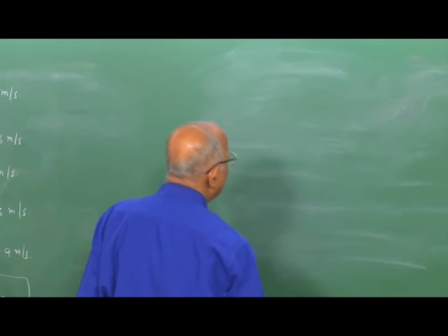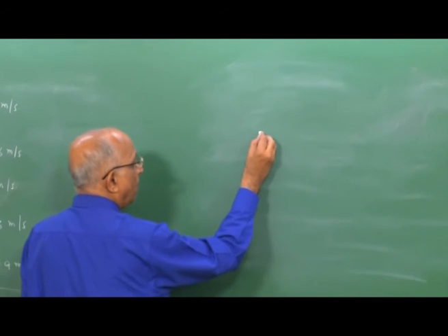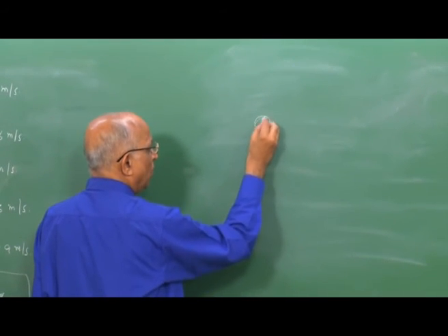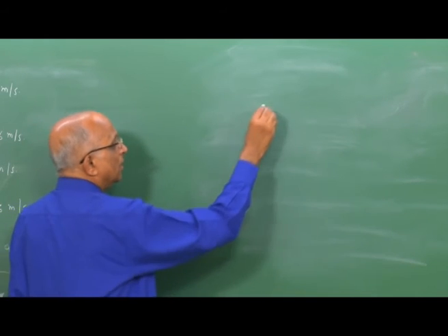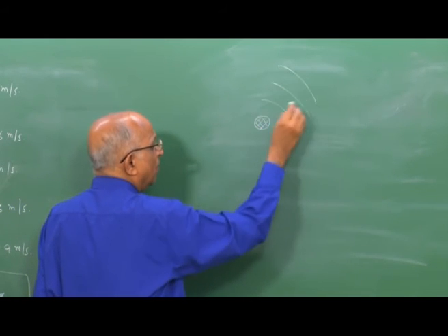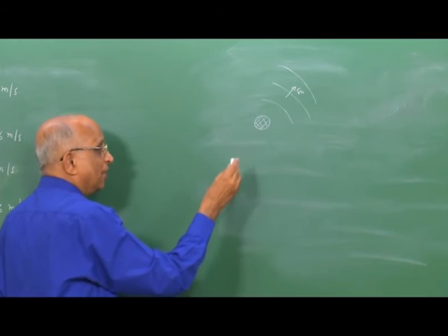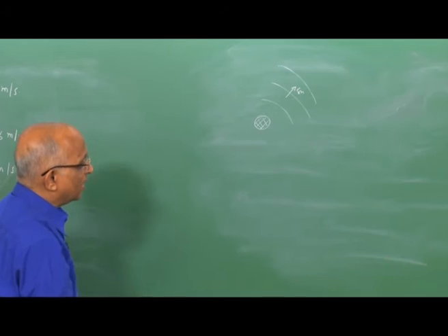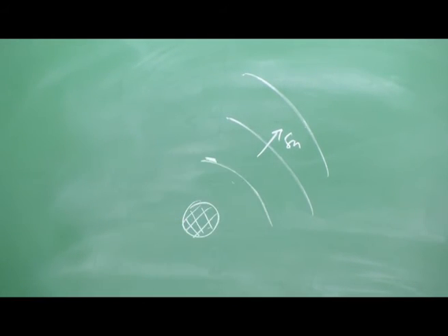Let's again not lose track of the problem. I have a particular volume, I want to find out what is the critical ignition kernel such that a flame propagates out. We are now able to find out the value of SU, or we say, well, ST will be much larger than SU. Can I also find out the thickness of the flame which propagates out, because that will help me to do this problem.